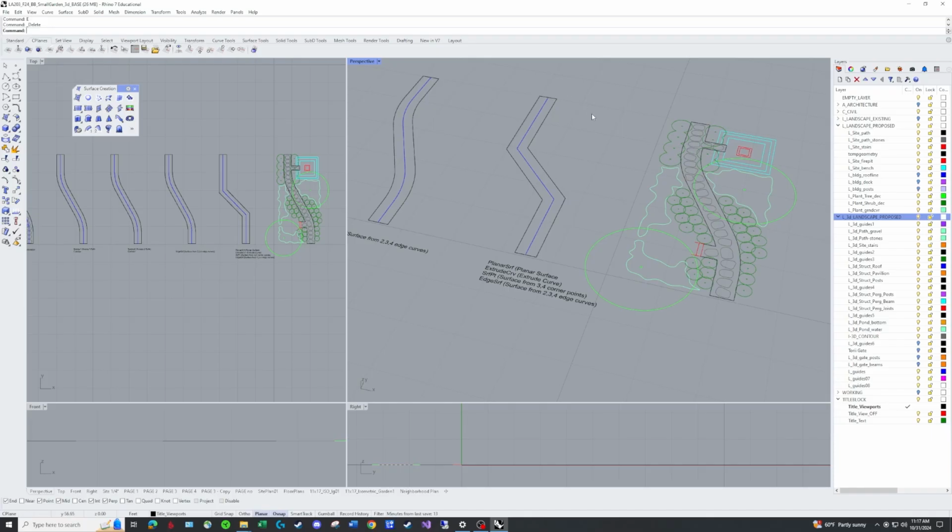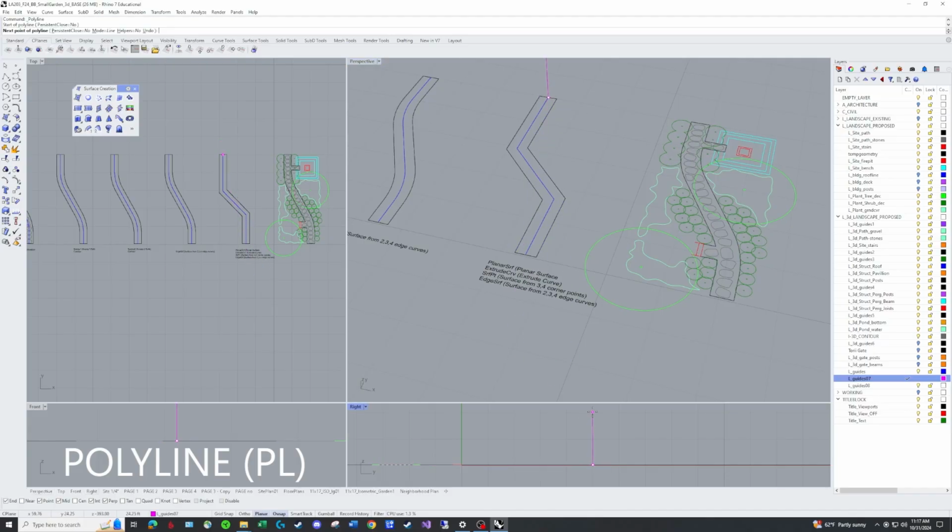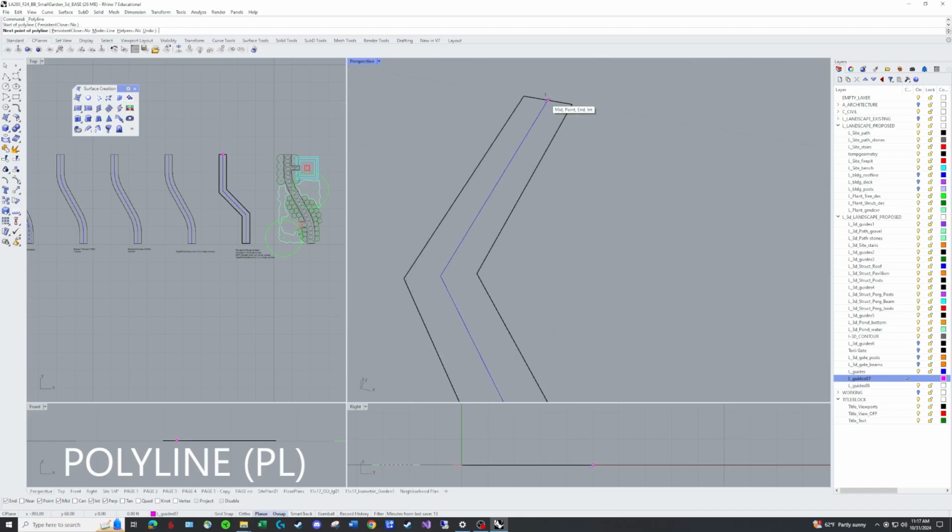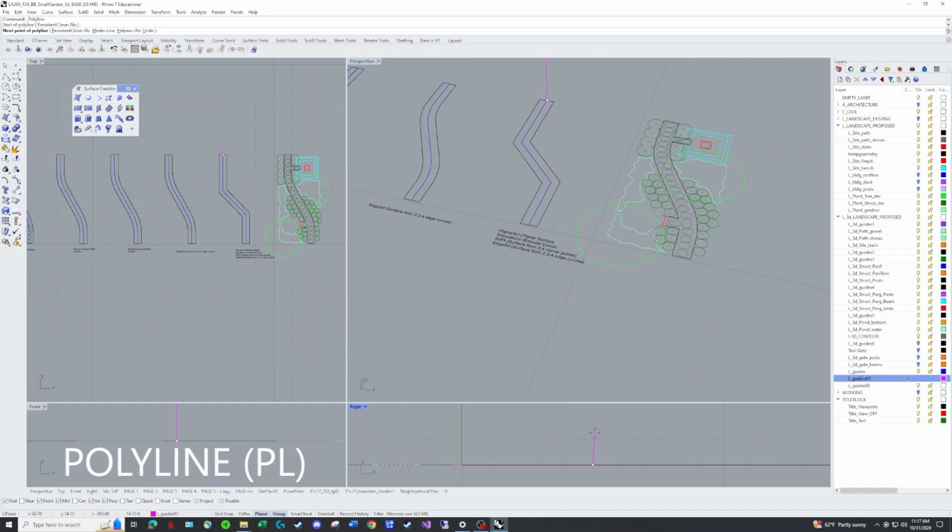So I'm going to use this as my guide layer. What I know then is that this point right here will be 18 inches. And notice I use the 3D to get the place that I want. Use the O snap, and then I'm going to type in 1.5 and hit enter. And what it's asking me to do is say, which direction do you want to go? I can go all over the map here and be like, what am I doing? Why am I doing this? But what I actually want to do is go directly straight up, which is why I have my cursor down in the right